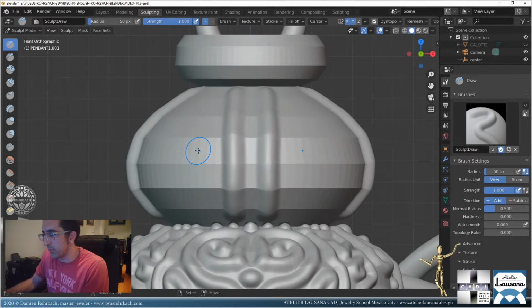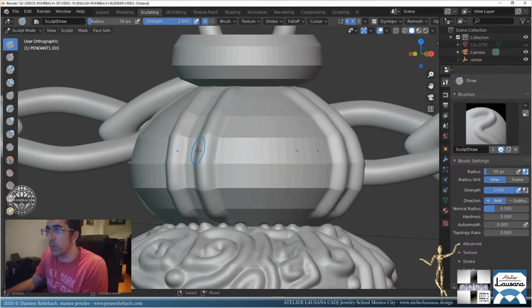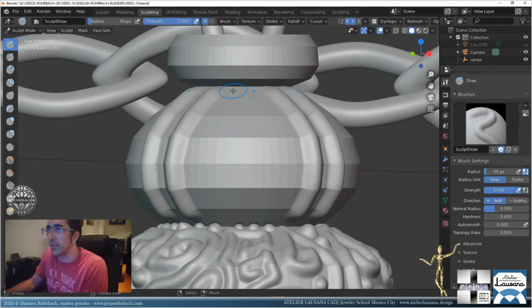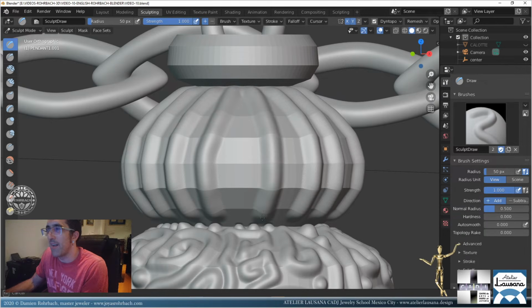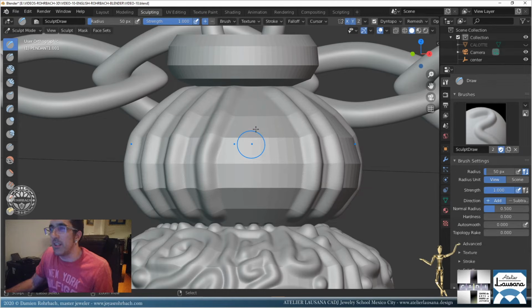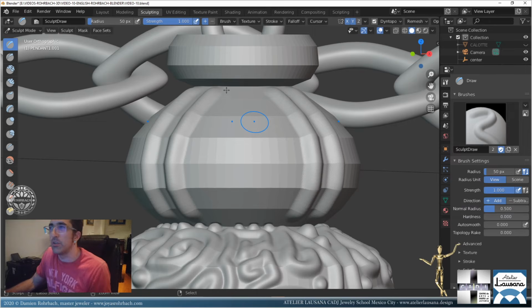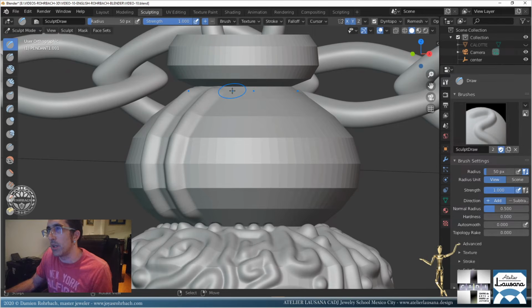Okay, now go front view, but use the 3 key, and with the numpad, when you hit 3, your view is going to rotate, it's not fitting the way I want. It's going to rotate evenly. Then you hit the 5 key to get the orthographic view again.